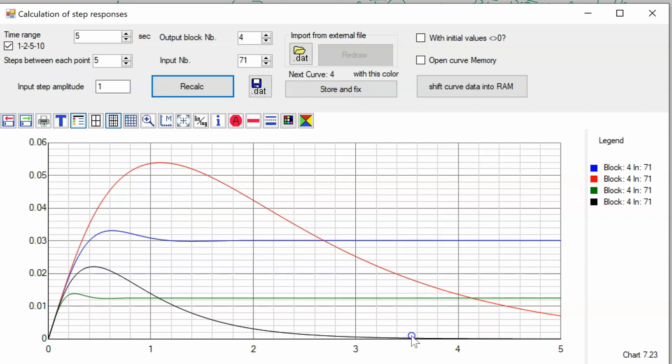This larger controller gain makes a smaller control error in the disturbance behavior. The PI pulls down the output to 0 as desired. I want to have it. And the PIDT1, of course, here is much faster than PI. So here you can see for the disturbance behavior, the PIDT1 is just the best so far.